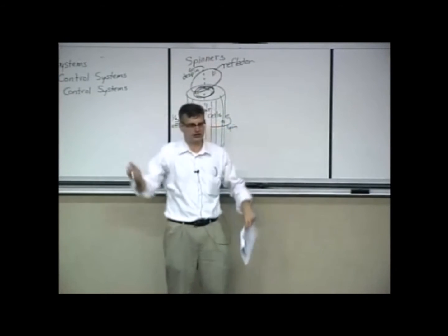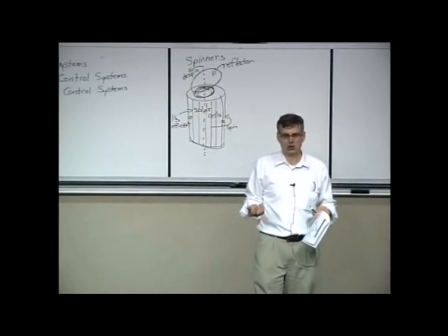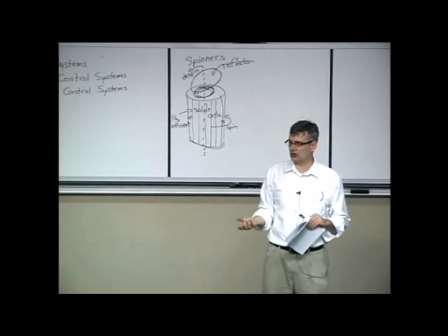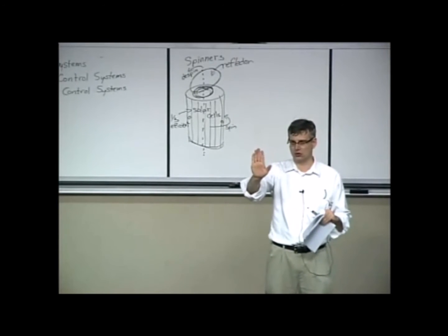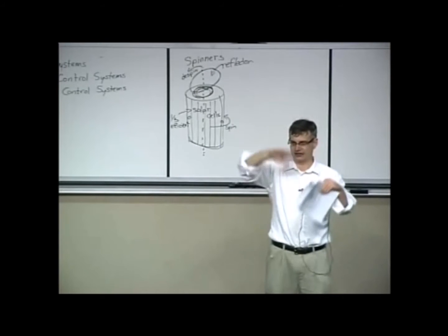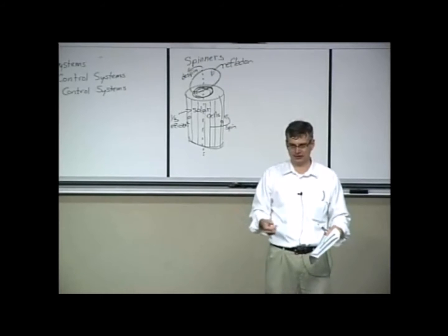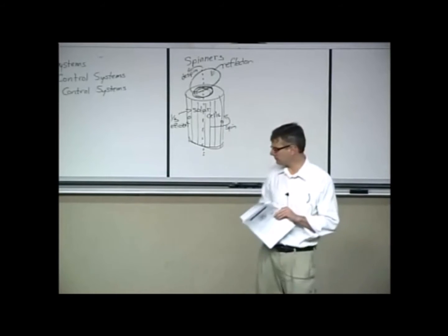Now, how do you always make sure that it's facing towards Earth? You have to equip your satellite with some sensing systems. Quite often, an infrared type sensor is used to actuate the antennas and figure out which side the Earth is on. The Earth is relatively hot compared to the blackness of space, and so it's relatively easy to build a sensor to actuate the position of the Earth.